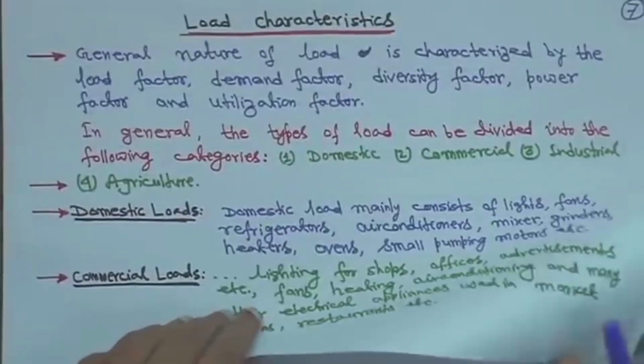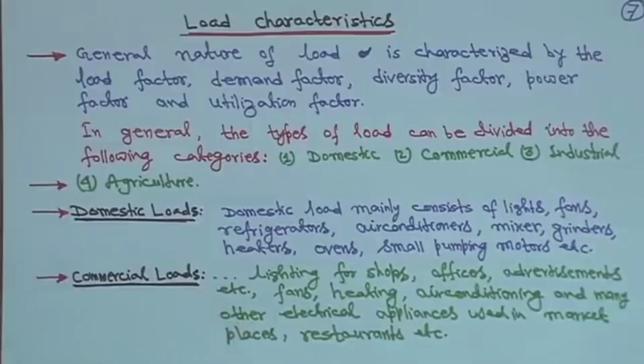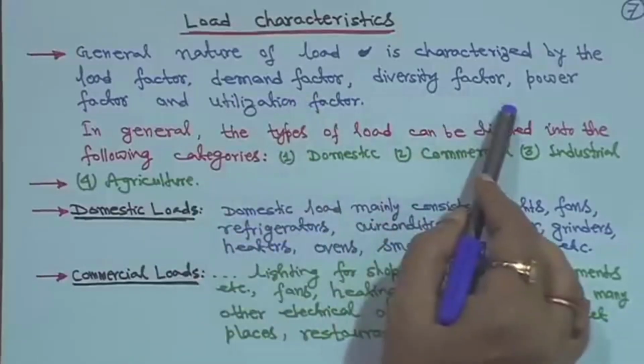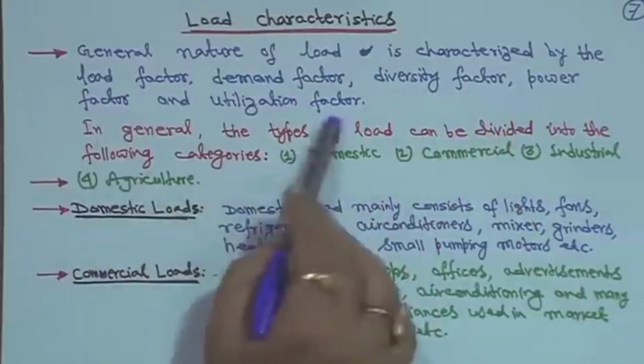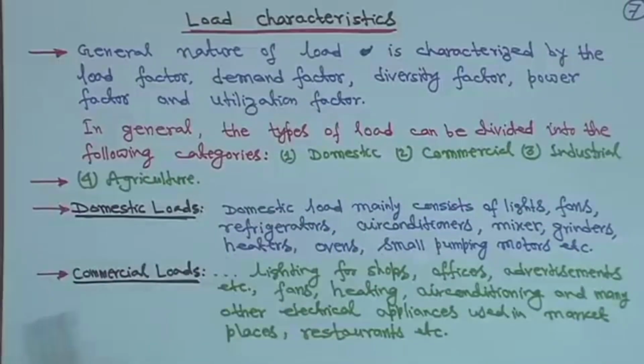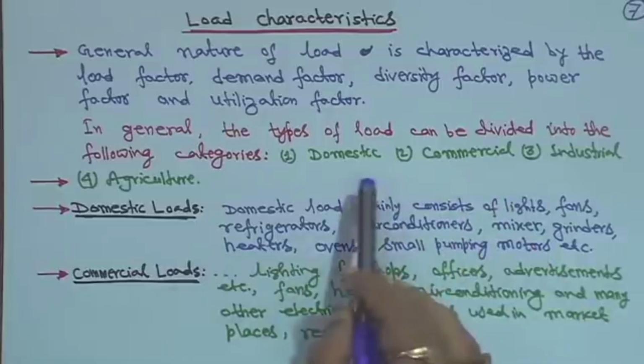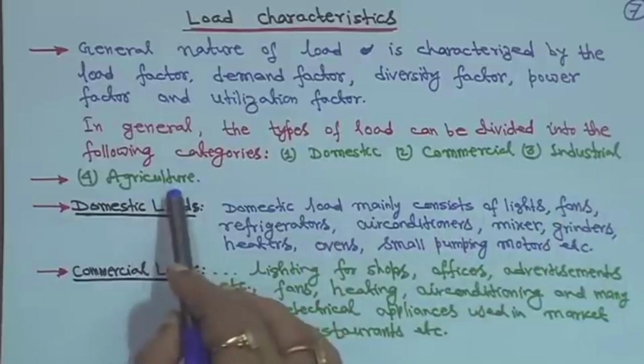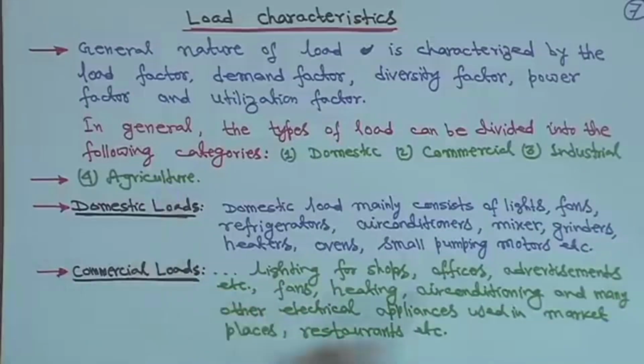Next is load characteristics. The general nature of load is characterized by load factor, demand factor, diversity factor, power factor and utilization factor. There are some more factors, later we will see. In general, the types of load can be divided into four categories: domestic, commercial, industrial and agriculture.